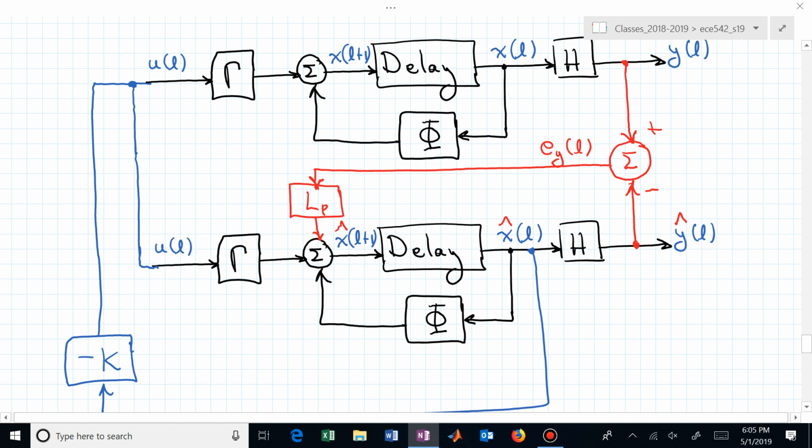Well, let's just use x hat as if it was x and feed that back through this full state feedback gain matrix K that you better know how to design on the final. You need to be able to design a K, assuming we could go in and access x. We're throwing that away and saying, let's get real, let's get more practical.